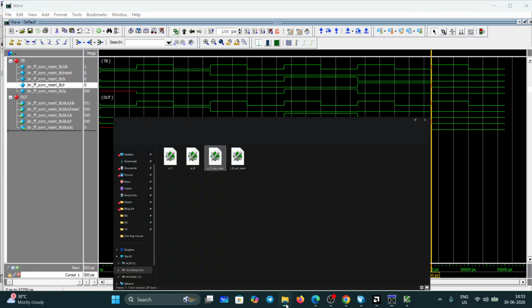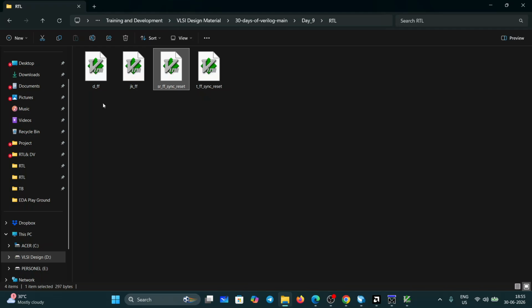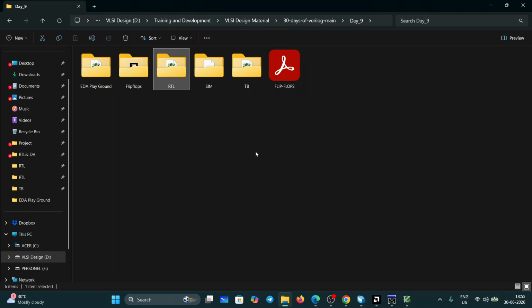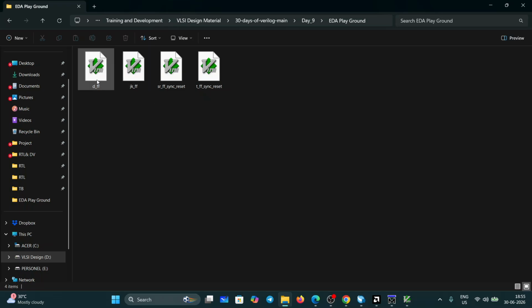Okay. Next, we'll go with D flip-flop. Okay. So how do you get the D flip-flop from SR flip-flop only? So in the SR flip-flop, when S equal to 1 and R equal to 1, that is an invalid state. Okay. So in order to not use that invalid state, we are going for the D flip-flop. So in D flip-flop, we are connecting S and R with an inverter in such a way that there are two possibilities. That is S equal to 0, R equal to 1, or S equal to 1 and R equal to 0. Okay. So that we also call a sequential buffer.